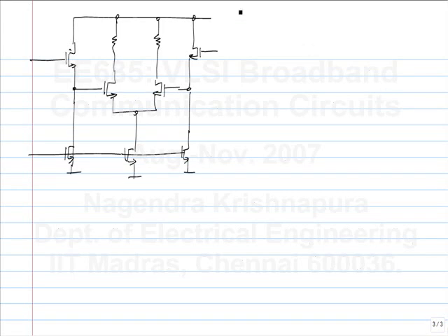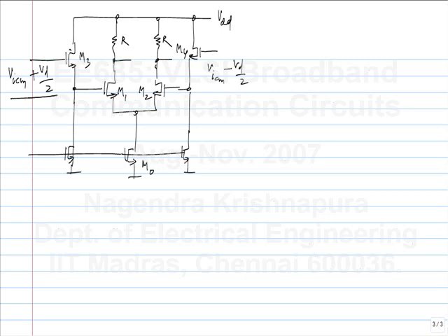That depends on the value of the supply voltage. What is the constraint now? We have to just reevaluate the constraints. Now this is again driven from a similar gate. What is the value of this? VICM plus VD by 2? No, VDD. What is the value of this? VDD minus I naught R. Now what are the constraints? We can reevaluate the same constraints. What is the constraint for M0 being in saturation?